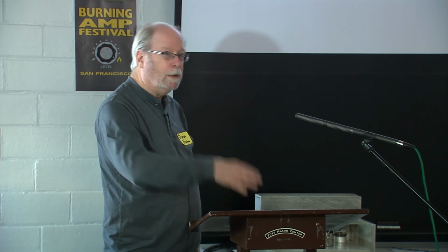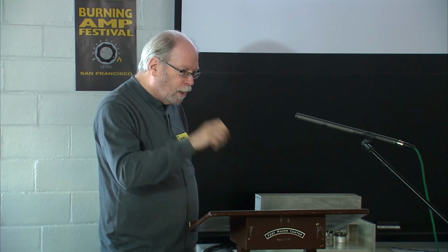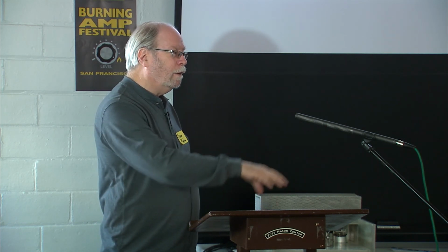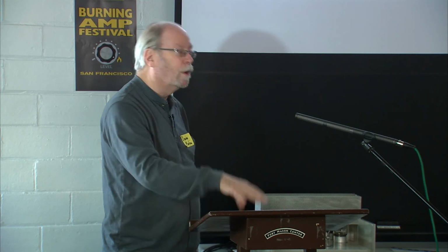I mean, it's kind of crazy. Here we have people struggling with really complicated passive crossovers going to complicated speakers. Your typical $100 Bluetooth speaker has 3 or 4 amplifiers and a very sophisticated DSP crossover doing things you can't even do with those traditional analog solutions. There, each amplifier is very carefully tweaked to work with its target speaker. The whole thing is optimized. The amplifier costs about $1.50, and there's almost as much money in the passive components on the output of it to make it all work. But they're far more sophisticated than what we're doing in this high-end audiophile realm in that sense.